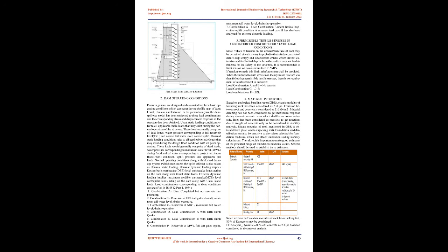This report deals with the stability of dam blocks for all the static and dynamic seismic forces along the river flow. The analysis has been carried out to ensure that certain mandatory requirements mentioned later in the report are met and that the dam meets its safety requirement and achieves its performance objectives. The mandatory requirements ensure that the dam is safe against all imposed loading including the maximum earthquake and that the stresses are within permissible limits. Finite element analysis software Midas FEA NX has been used to carry out the present analysis.